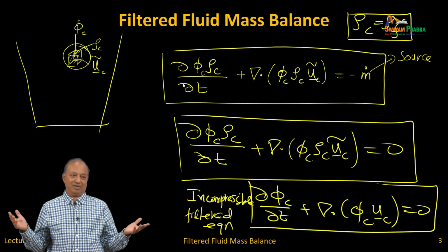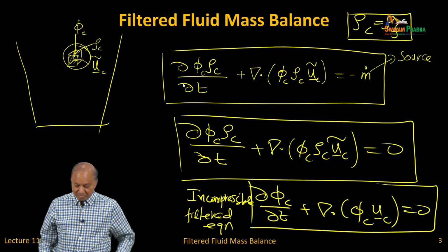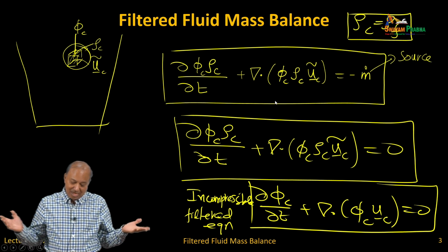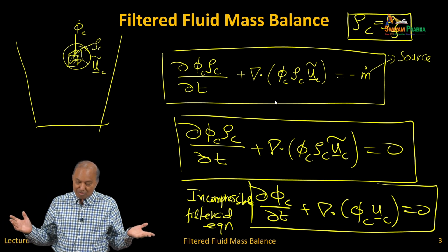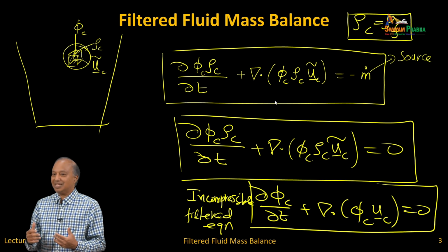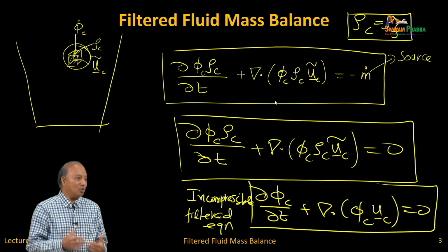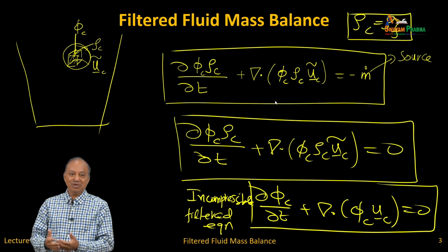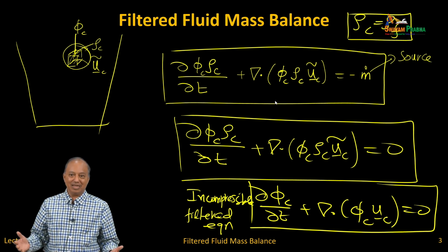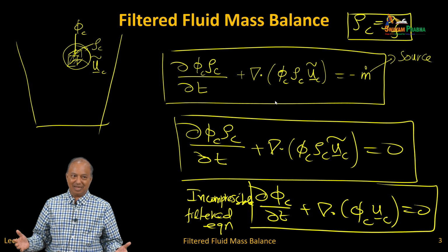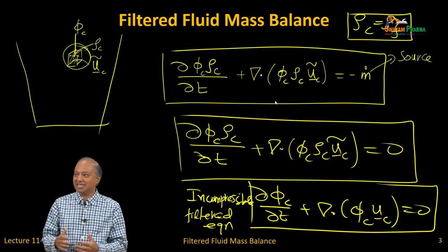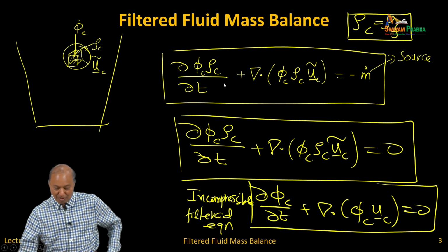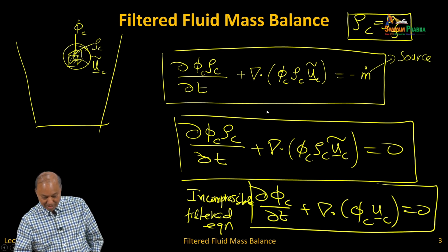We solve it everywhere. And this equation looks like a standard equation. Our goal is always to get equations that look like standard equations, so that you can push it into Fluent or any code that you can simulate. So that all the CFD techniques of a single phase can be used for multi-phase as well. And that is why we want to write this in this form.